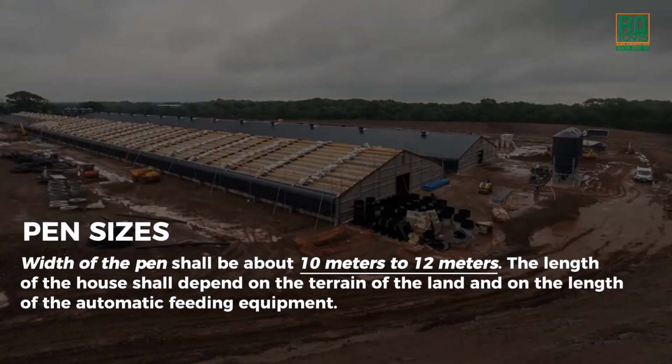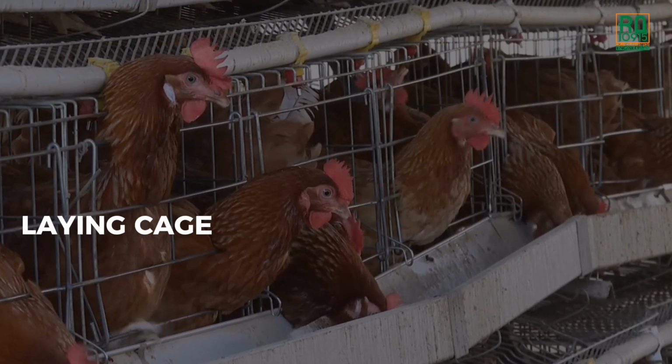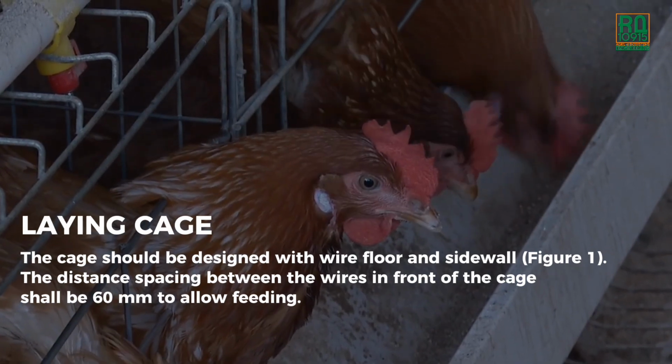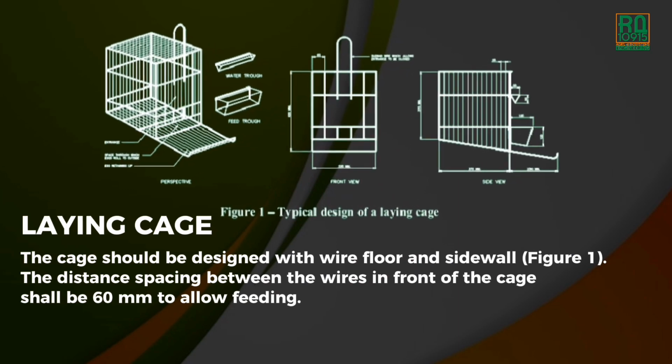The length of the house shall depend on the terrain of the land and on the length of the automatic feeding equipment. Laying cage. The cage should be designed with wire floor and sidewall as shown in Figure 1. The distance spacing between the wires in front of the cage shall be 60 mm to allow feeding.